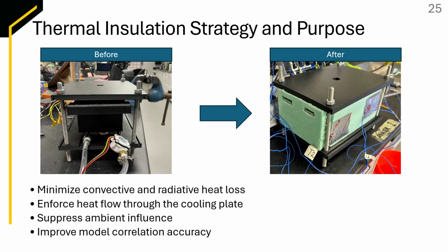For the thermal insulation strategy and purpose, we can see the before picture where the mini module and the cooling plate are exposed to the outside surface, and the after picture where everything is enclosed in the R5 foam. This is going to minimize the heat loss, enforce heat flow through the cooling plate, suppress ambient influence, and improve model correlation and accuracy.